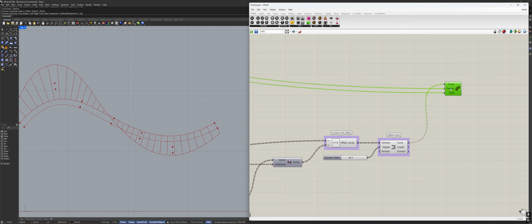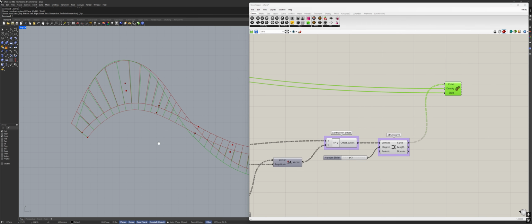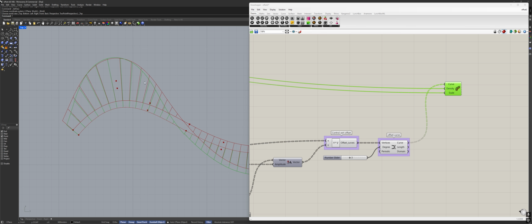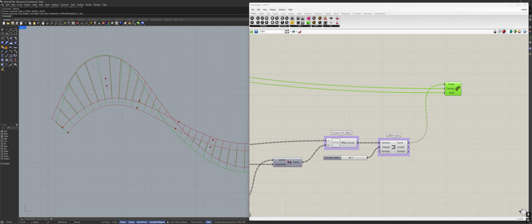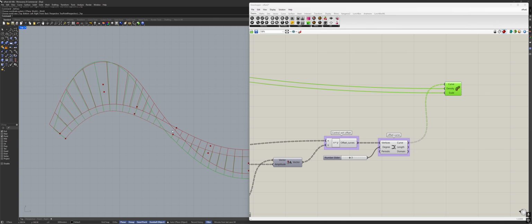And in fact, if I activate the curvature comb, you're going to see that, yeah, it's much more accurate now, but the gap is even bigger. So now this is a really significant break in curvature and a pretty significant break in tangency. So yeah, we sacrificed the gap and continuity for the quality of the curve. It breaks even more. But this is a second option for you.